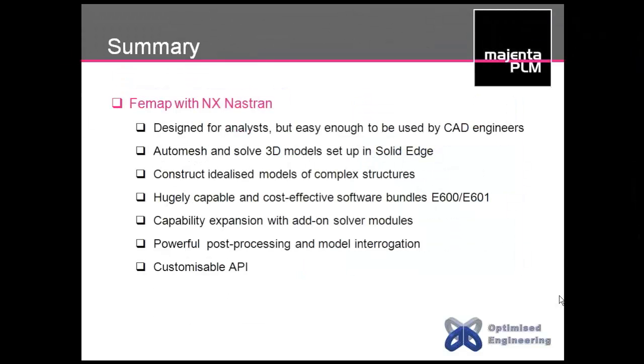So to sum up then, Femap with NX Nastran is designed for analysts, but it's easy enough to be used by CAD engineers. You can bring in Solid Edge models, 3D models, and auto mesh and solve in much the same way that you would with an embedded CAD FEA system. But you can move things forward to generate idealized models of complex structures, as we've seen.